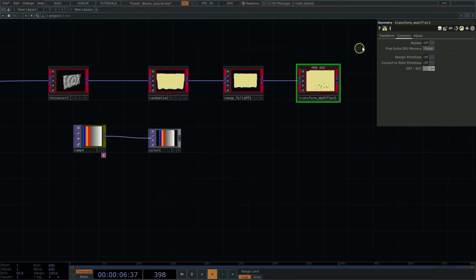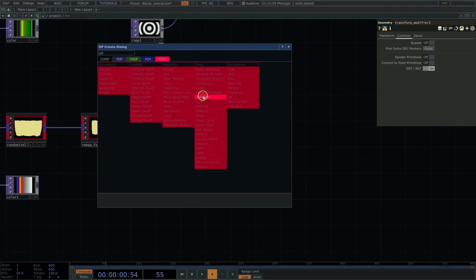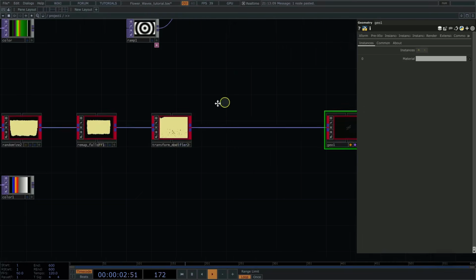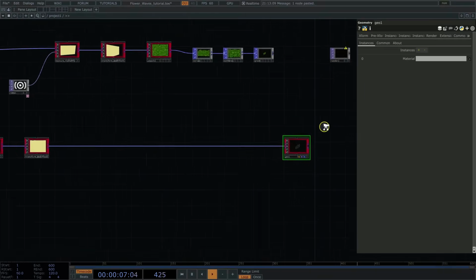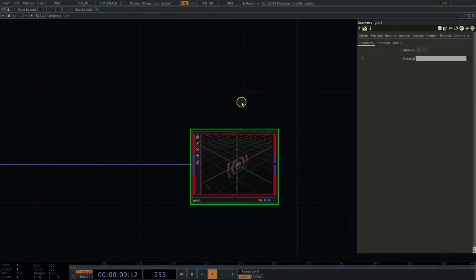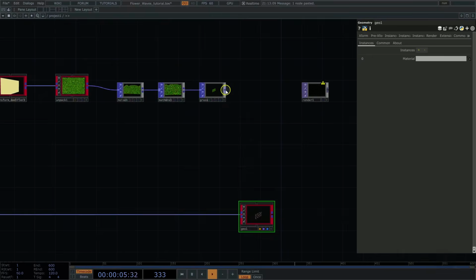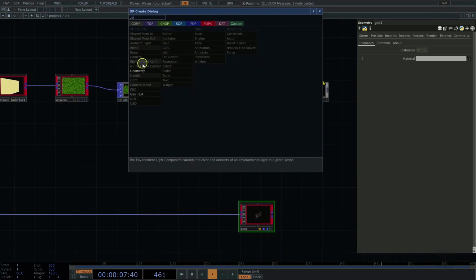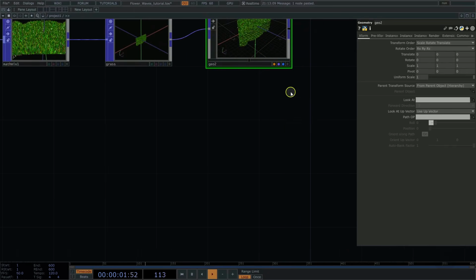Connect a POPX geometry comp for the flowers. We need this one specifically, not a regular geometry comp, because the flowers are still a packed POPX geometry, not a regular pop geometry. A standard geometry comp won't work here. While we're here, drop a geometry comp for the grass too. That one's the standard comp, since we already unpacked the grass into actual geometry earlier. Connect the grass null into it.